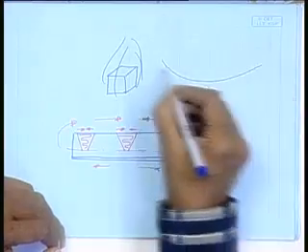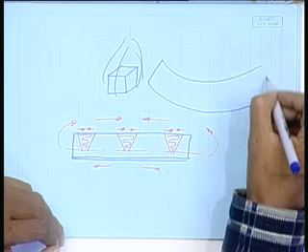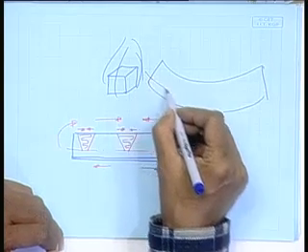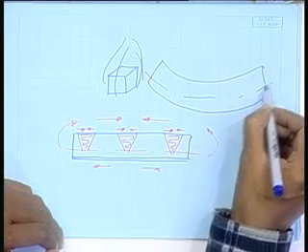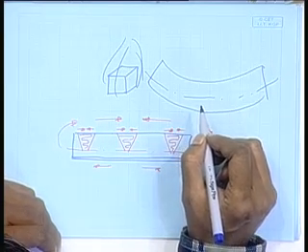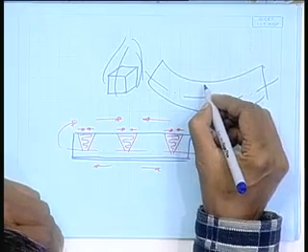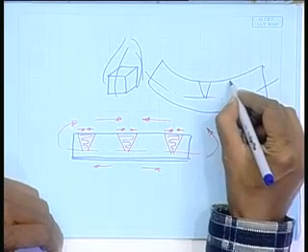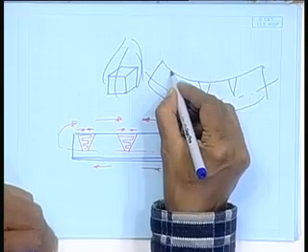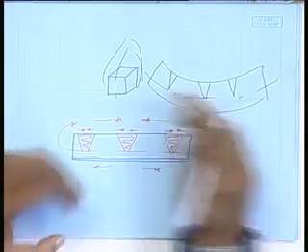So now again it becomes skill dependent. You will have to see, for a given bend shape, right, I have to first find out the neutral axis. That is pretty easy, one can draw the neutral axis. Then I have to work out how many such heating zones are to be implemented so as to get this bend shape, right.